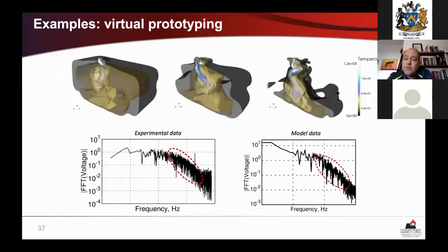The arc's motion causes quite a distinctive response in the frequency spectrum of the voltage and current signals, and we were able to use that response to design a detection instrument which we call DC ArcMon, and that can tell you whether or not you have an arc somewhere in your circuit. This can be quite a handy tool for indicating the presence or absence of an arc in cases where it's impossible to look into the furnace and determine that visually. So in cases where the arc region is obscured in some way by beds of feed material or banks of frozen slag, or it's just too hazardous.